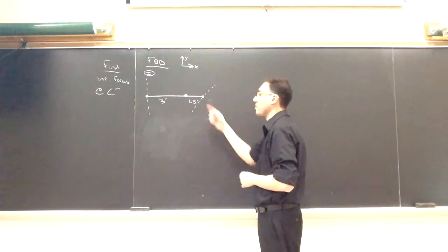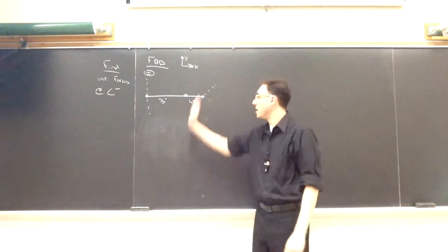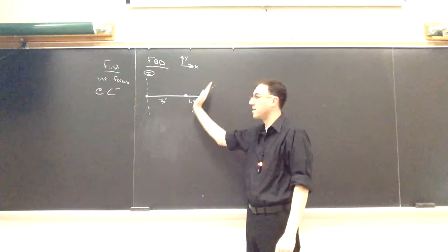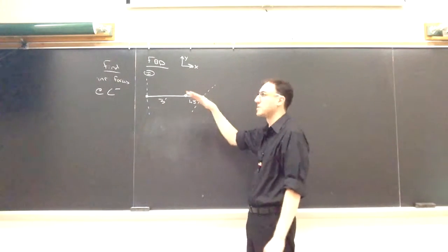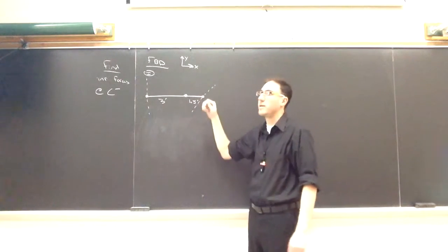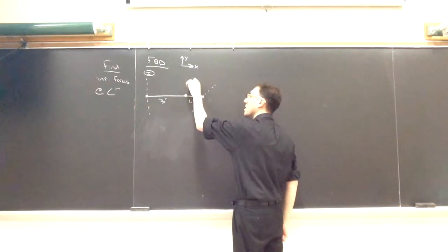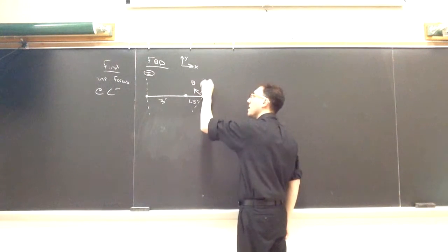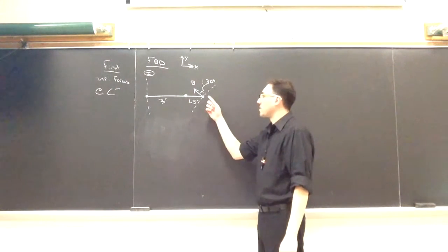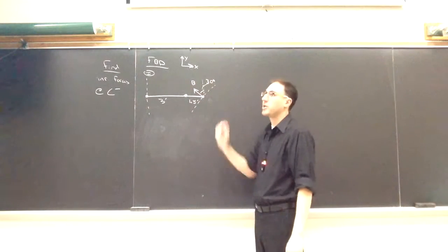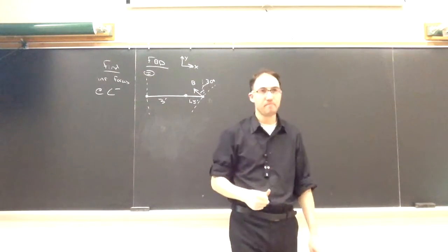What is the reaction or reactions at B going to look like? The rocker allows a little bit of motion along the direction of the surface, but it's going to act basically the same as a roller, at least for small amounts of motion. So it's going to prevent motion orthogonal to that surface. So I'll have some force pushing that I'll call B, that's going to be 30 degrees from the vertical axis. That covers B, and the rocker allows rotation around the Z-axis coming at us, so there's not going to be a moment at point B.